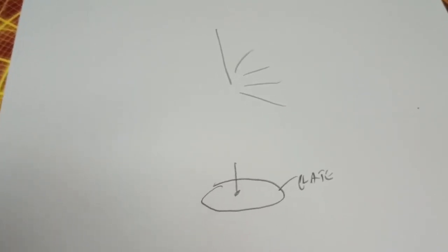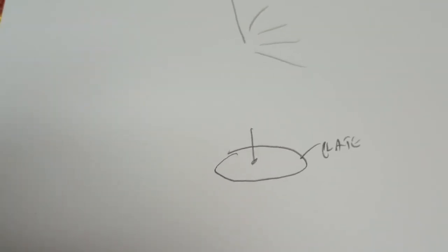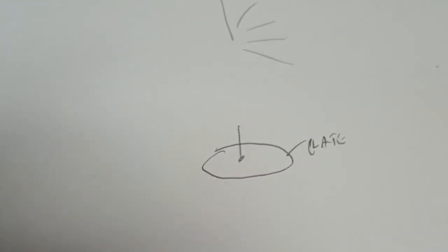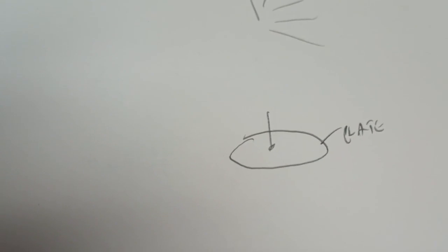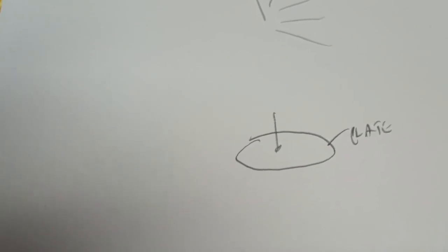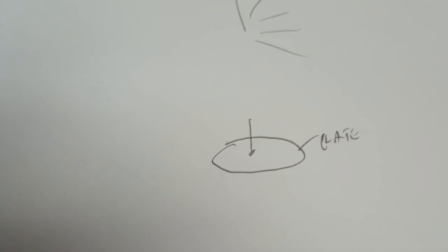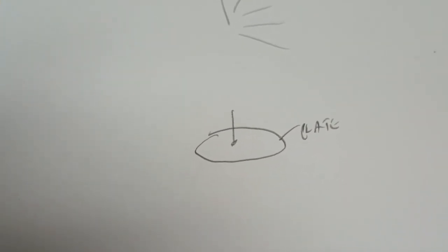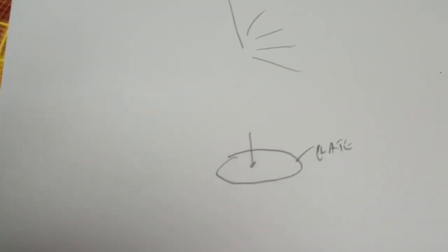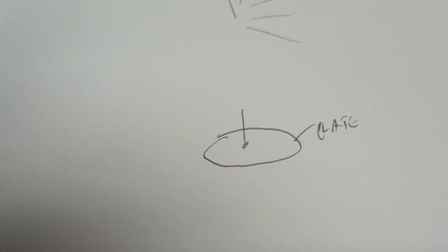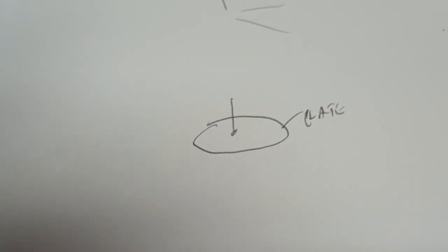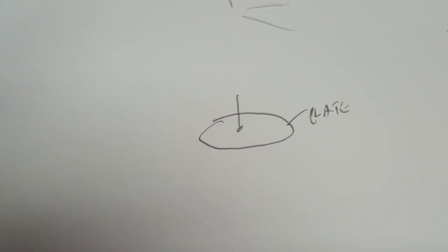Now you want to improve that, you put down a metal plate and perch that monopole on that plate. Now you've got a big, big surface area. Far more surface area than the surface of the wire. And this is part of the discussion of what's known as grounds of zero extent, grounds of small extent, and grounds of large extent. Putting out miles of wire in the soil makes a ground of large extent, arguably. This can be a small extent. This is what I have on my pickup truck with the Hustler ball mount antenna. The antenna's on a small metal plate, and it just kicks butt. Beautiful matching on 20. I can almost work the entire band with low SWR.